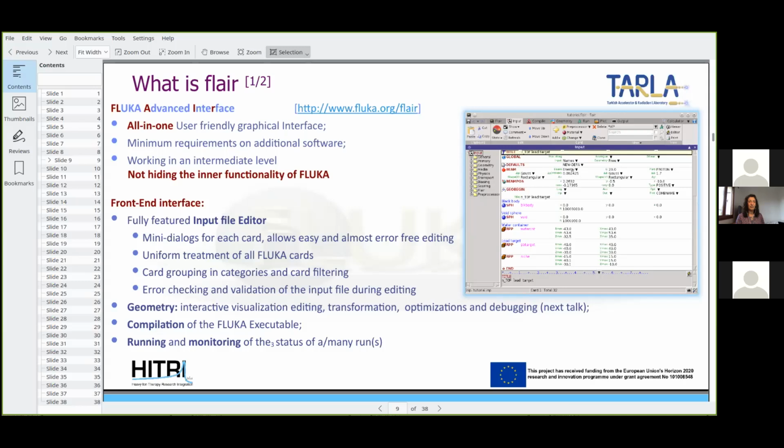The most crucial one is about geometry. You don't want overlaps of your geometry which are unphysical, protrusions of one region into another. And this is something that both FLUKA in general, but FLAIR in particular, can easily warn you about. Here you see how this input looks like. You define your beam position, various geometry patterns, and later on you define specific particles that you're transporting and looking at. And also here you define what it is that you're scoring, what physical quantity of interest is the one that you're saving. So this becomes all rather nice.